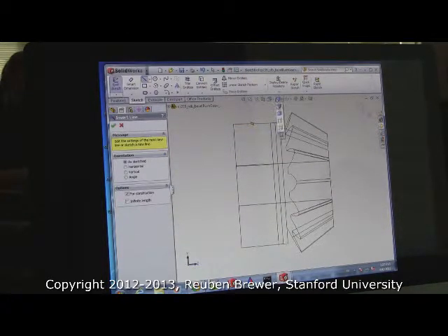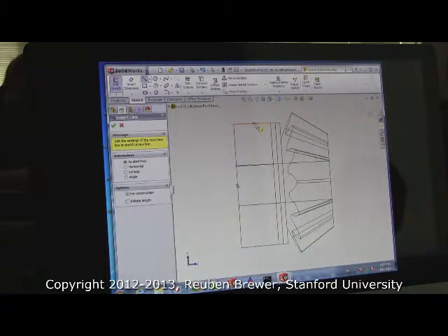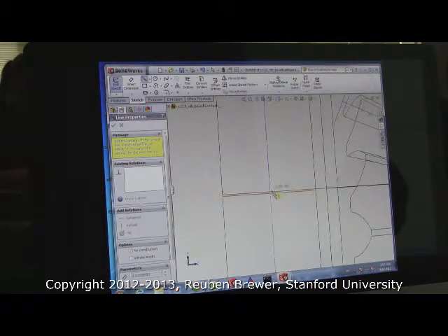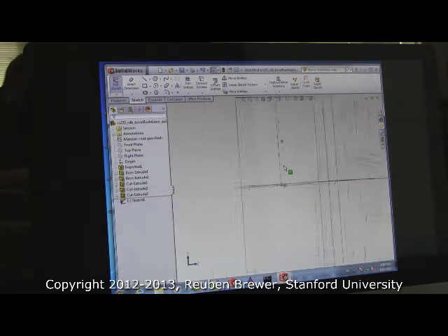So basically, I want to put a circle halfway in between this line and this line. Okay? So we're going to use a midpoint constraint. So in wireframe view, you take a construction line, and you see on my screen how it turns red and it wants to make me snap to right there. Snap there, and then zoom in and snap here on the inside.